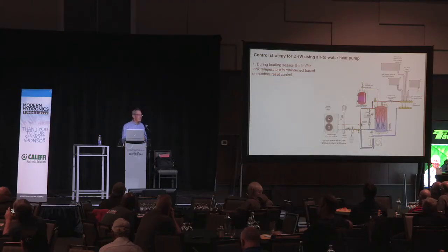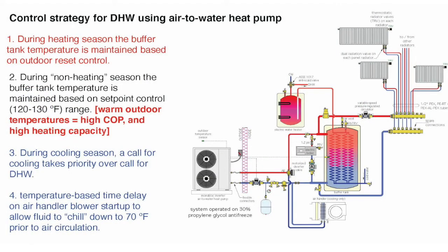Now, the other thing you see at the bottom of that schematic is a chill water air handler. And the diverter valve simply determines which way the output from that heat pump goes. In a cooling mode, the diverter valve would route that down through the coil in the air handler. And it's important to understand, if you're going to go direct, notice that the buffer tank is not participating in the chill water cooling. All right? We're not buffering chilled water in this system. So we're counting on the heat pump capacity being matched to the coil capacity in that air handler.